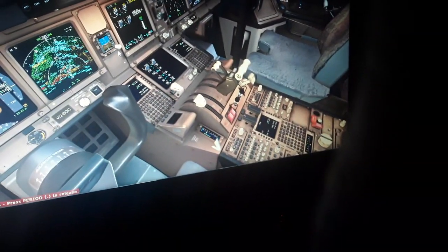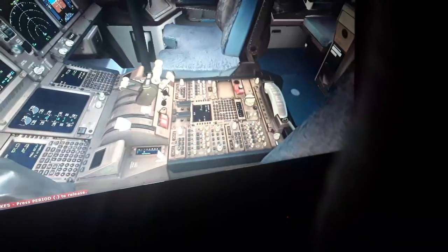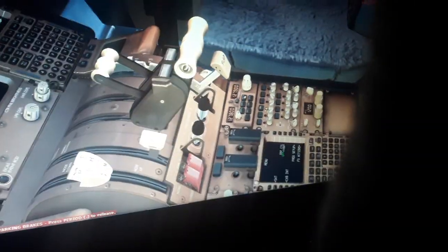We cancel the thrust reverse like this. So we have the parking brakes, the horizontal tail trim stabilizer, the fuel control for the engines, left engine, right engine, fuel control switches, the stabilizer trim, the cutout switch for the horizontal tail, the C and the R. So if you have a malfunction of the C or the R hydraulic system, which drives the auto trim function for the autopilot and the auto throttle, you disengage from the normal to cutout, so you only have the manual